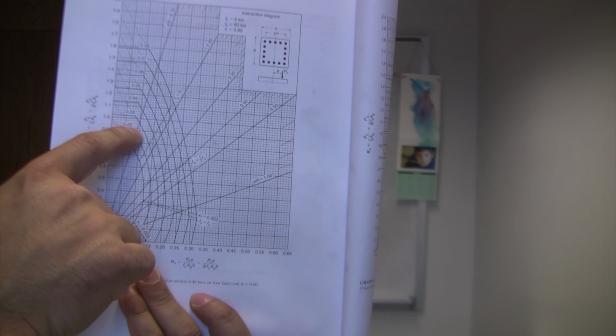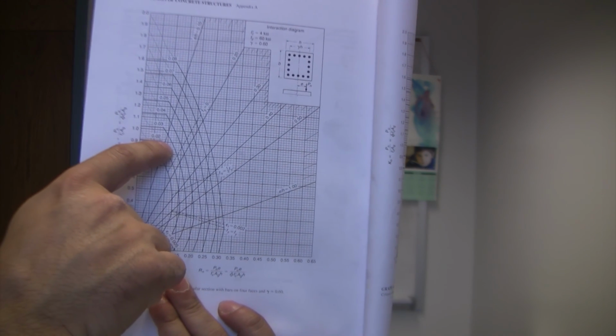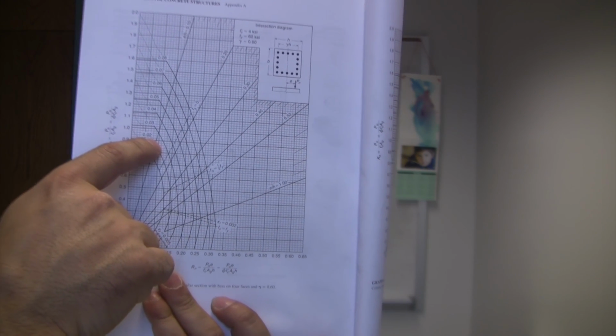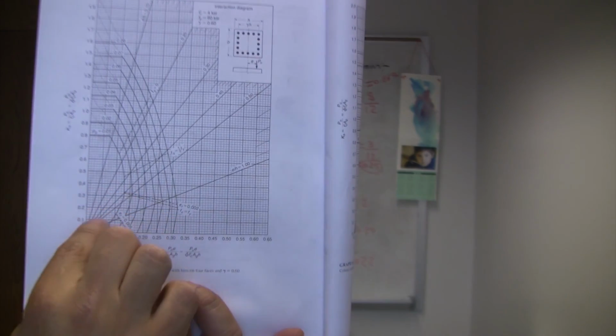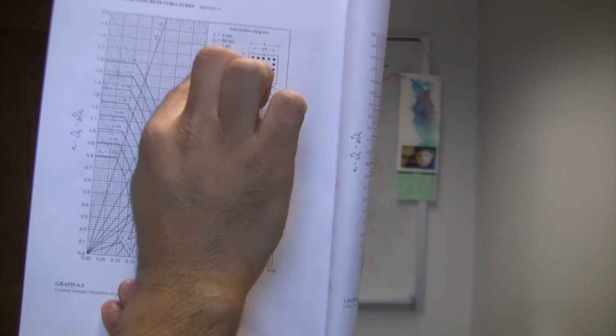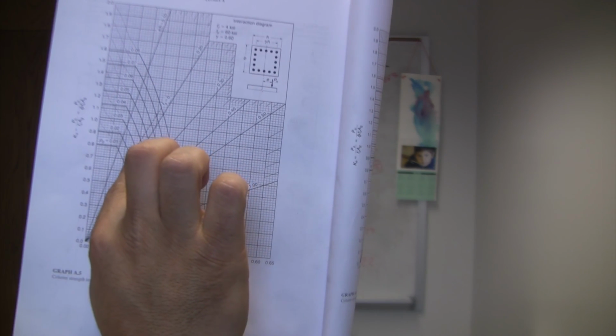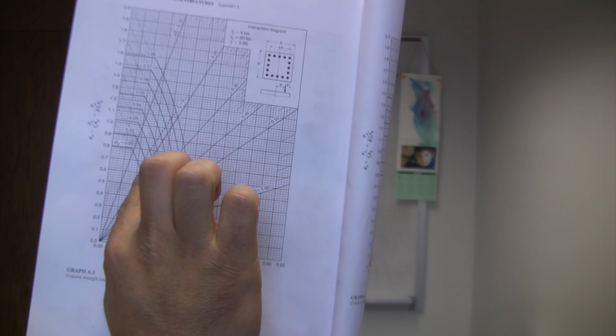So you can, to your best, try to locate the 0.022, which is a little bit above 0.02. And e over h, as you can see, 0.1, 0.2, and this is 0.3. So 0.25 is somewhere a quarter of the distance from here to here. So you can determine where that is with the rho that you have in here.